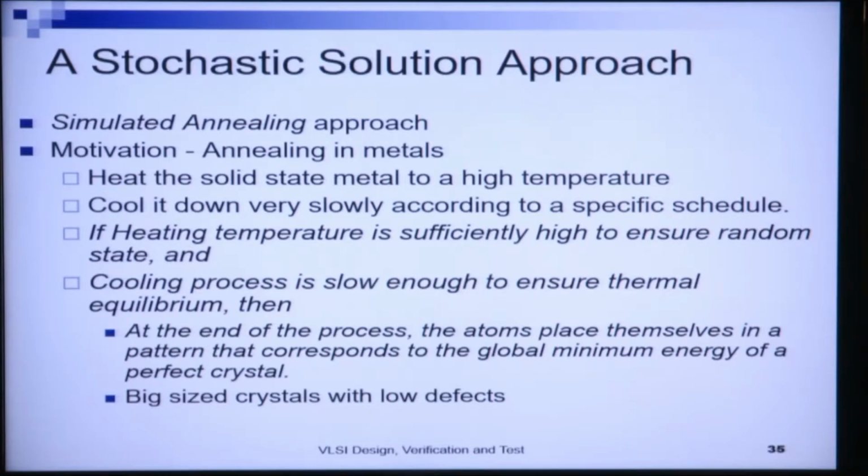And then if the cooling is slow enough to ensure a thermal equilibrium, then at the end of the process, the atoms place themselves in a pattern that corresponds to the global minimum energy of a perfect crystal. And with this we obtain large size crystals with low defects.